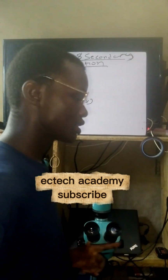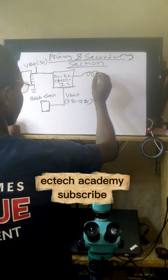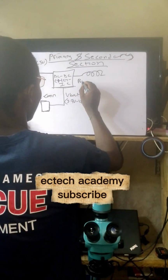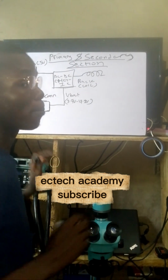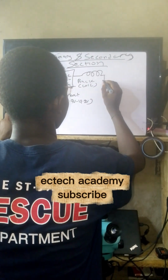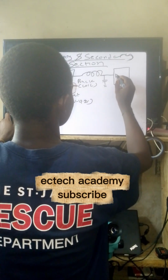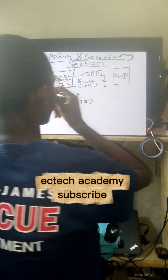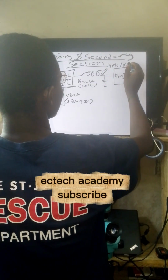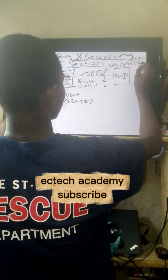Let's assume that the charging IC is also responsible for giving out VPH power through a coil, and this coil is called the buck coil. I believe that you know how the buck coil works. We have an output capacitor here, and this line is going to the power management IC. This line is called VPH or VSYS. The voltage also is between 3.7 volts and 4.2 volts.